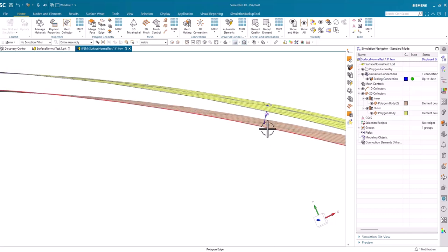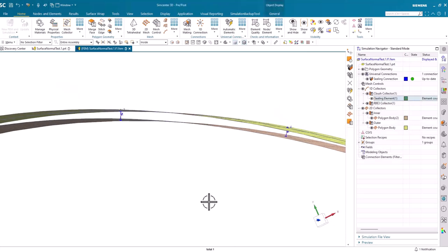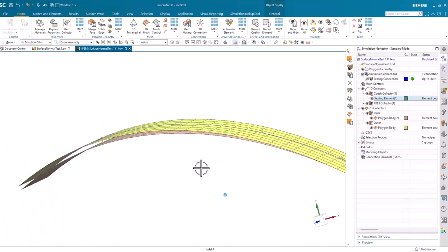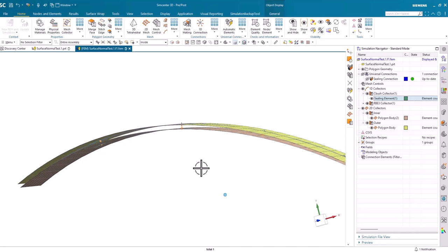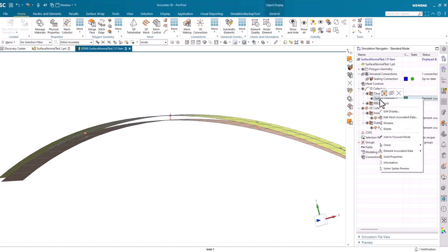So I have a spring element with a length. It's not a coincident noded spring, and also we'll have a coordinate system at each of those springs when I go to solve this model, but right now not evident. Those coordinate systems aren't created until we actually write out an input file.